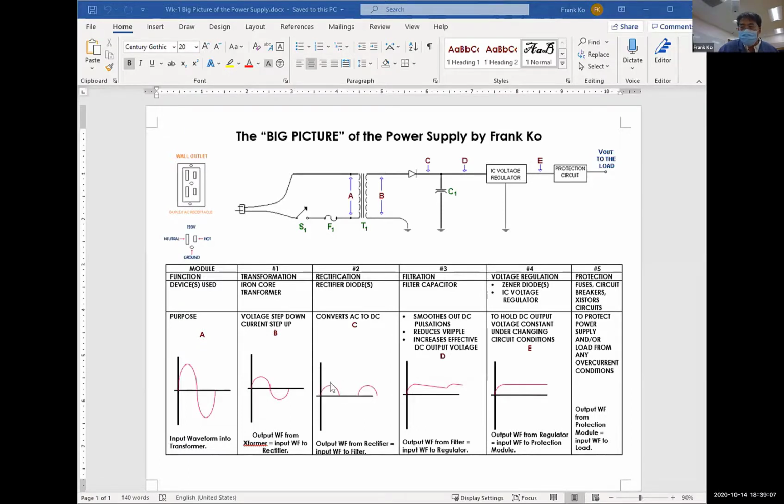If you imagine this red line were a flexible piece of string, and if you could flatten it out, the amount of space underneath this curve, flattened out over a straight line, is about 1/3 of the way up, okay? So the effective DC here in waveform C is approximately 1/3 of the way up.